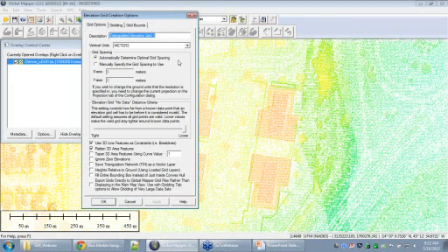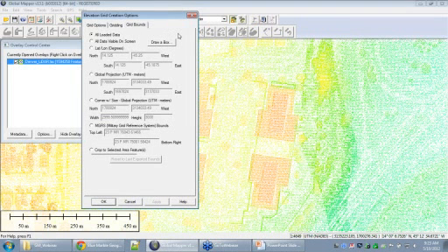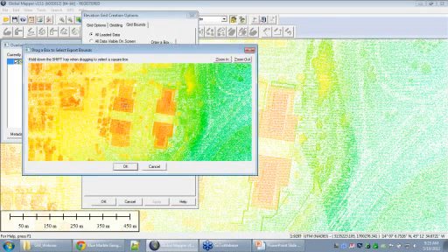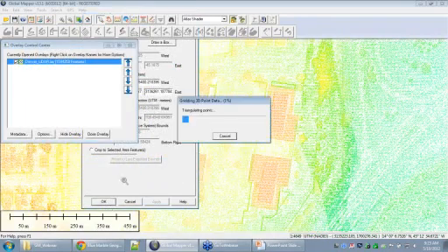So I'm just going to let Global Mapper do the work for me here to figure out what the best spacing on that is, and it's going to come to that from how close my points are together in the file. We have some options for if we want to create this as tiles. That might be useful if you're working with a very large area covered by high-density LiDAR point clouds. And grid bounds. We can focus on simply a smaller area if we want to just create a localized terrain model for that. We can narrow that down by simply drawing a box on the screen. And I'm going to do that just in the interest of time here. So I'm going to focus on this area around these buildings.